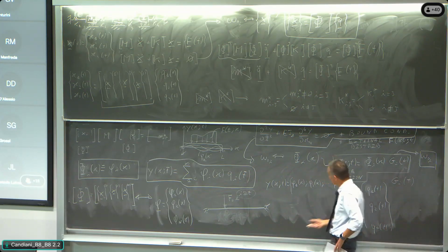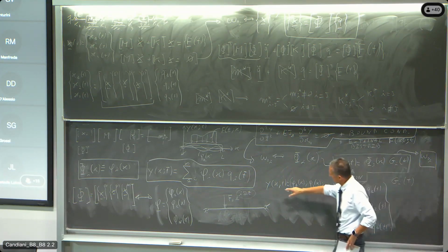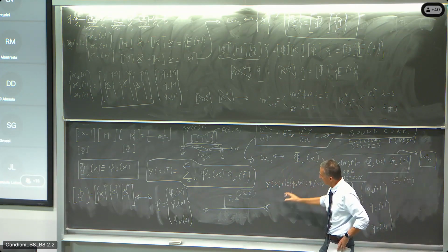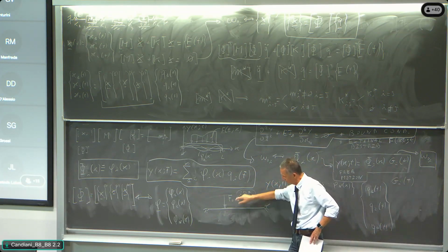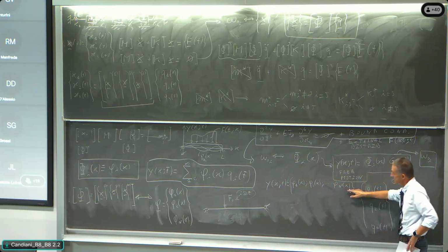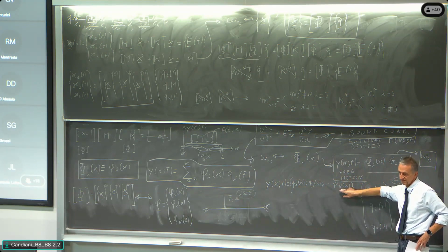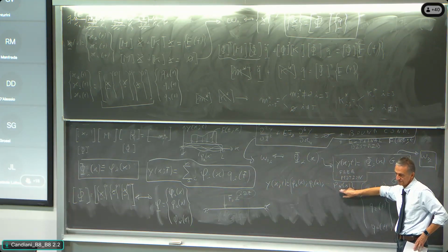All right? And so when I pretend to write that the actual response of this structure to this excitation is written through the superposition of all the modes, you see that now I stopped here, at n. I will never use all of them to infinity. It's not possible, it's not feasible, it's not useful.